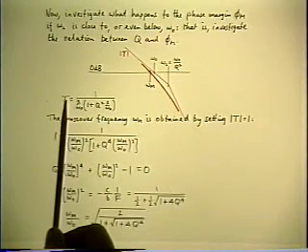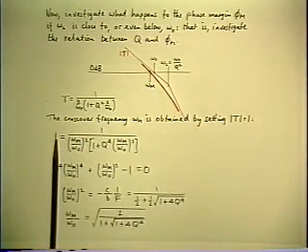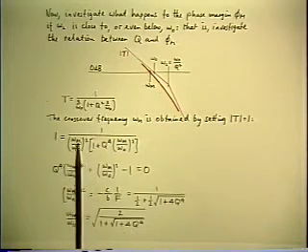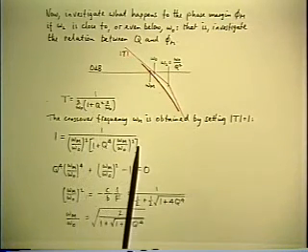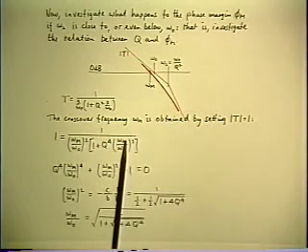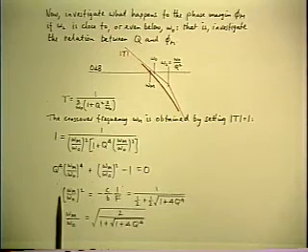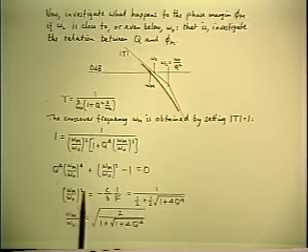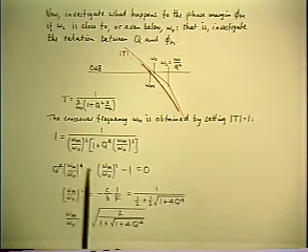So you set the magnitude squared of T equal to 1, and this is the magnitude squared of the right-hand side. And this occurs at the crossover frequency omega m, so you have to invert this and solve for omega m. And you find that it's a quadratic in omega m squared.